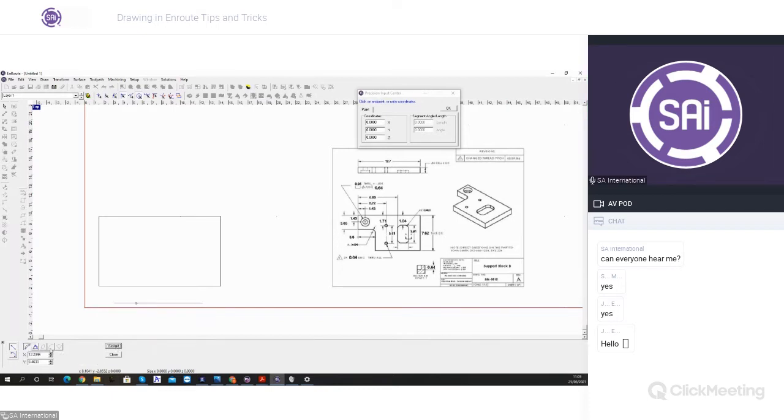and we'll hit OK. And then, of course, we can draw our next segment going up by 90 with a length of 7.62. And then going left again, an angle of 90, and then with a length of 12.7.